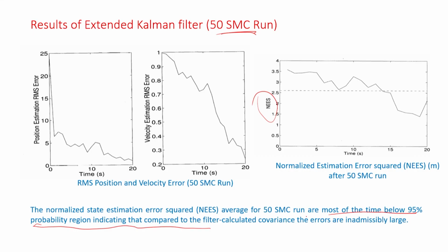Here it is dropping. You can see here, it is just kind of 95, it is not reaching the 95% mark. So, there is some issue. The issue is known even if you do not take a Monte Carlo run, by seeing your innovation error. Since your innovation error squared or norm of innovation, you can clearly see if it is losing its chi-square distribution